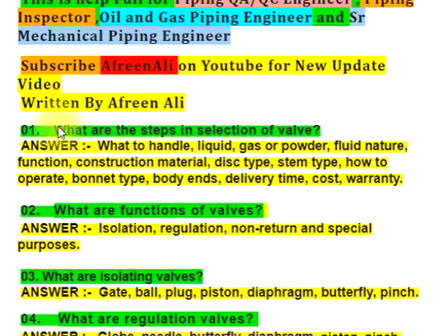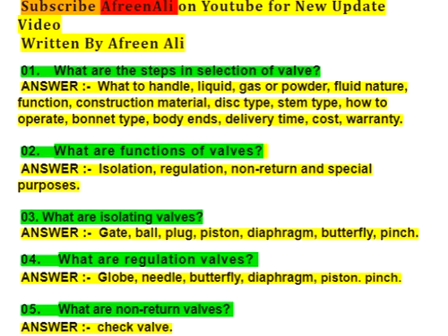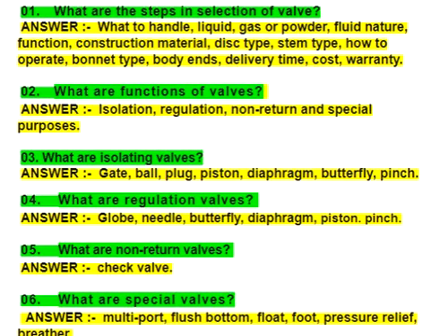01. What are the steps in selection of valve? Answer: what to handle, liquid, gas or powder, fluid nature, function, construction material, disc type, stem type, how to operate, bonnet type, body ends, delivery time, cost, warranty.